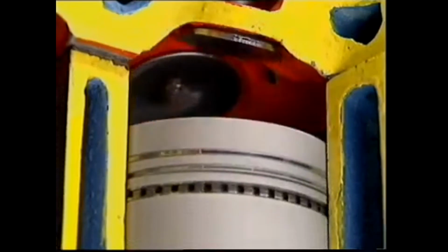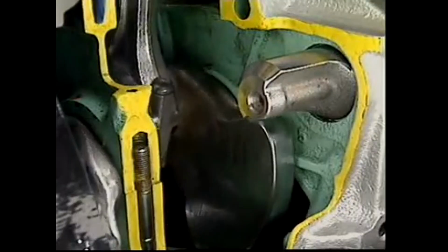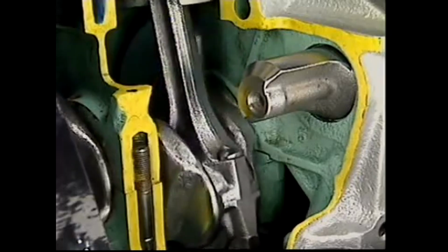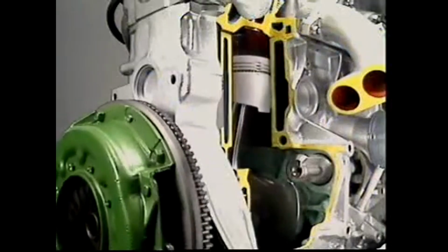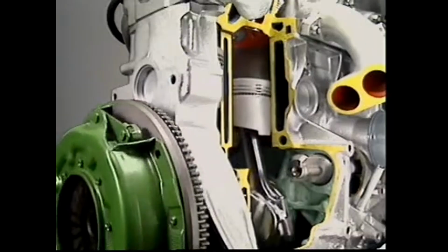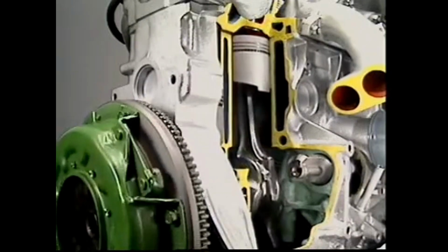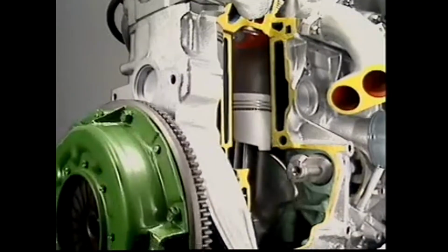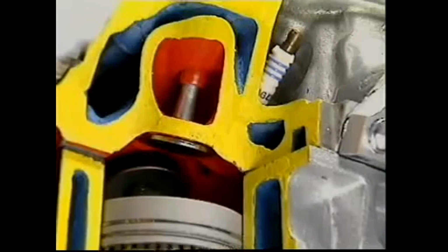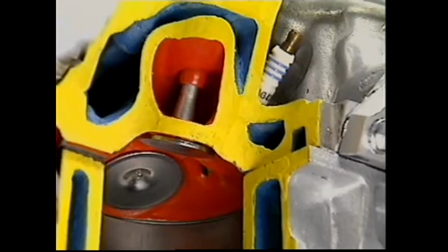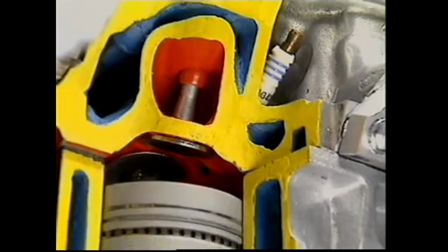The position of the piston is crucial, but what determines that? The crankshaft. It helps to synchronize all this activity in one cycle of a 4-stroke engine, from intake through compression, ignition, power, and exhaust. How many times does the crankshaft turn? Twice. It makes 2 revolutions. During that time, what happens to the valves? They open and close once.